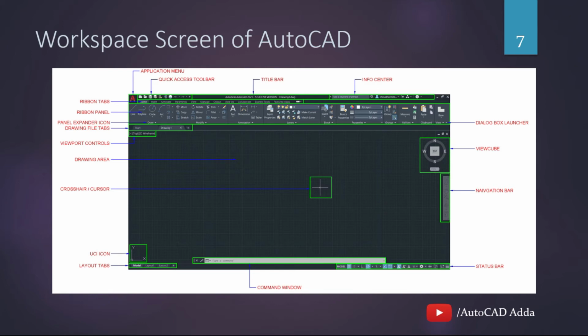Next, we have viewport controls. Here, you can select the direction to be viewed from, the number of viewports or the visual style. Multiple viewports help to view the objects from different angles and work on them at the same time. The visual style helps to view the objects in different styles, especially 3D objects, in 2D wireframe, conceptual, realistic, X-ray, etc.